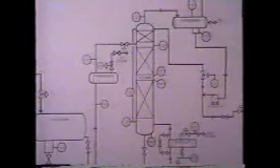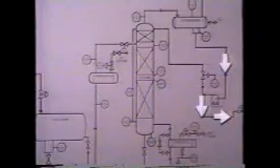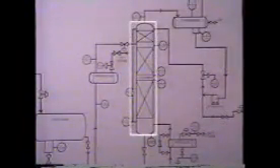This reduces the amount of liquid flowing down the column. When the reflux rate is lowered, the amount of overhead product being taken off increases. This reduces the overall amount of liquid in the column. Removing the excess liquid in the column may be enough to cure the problem.